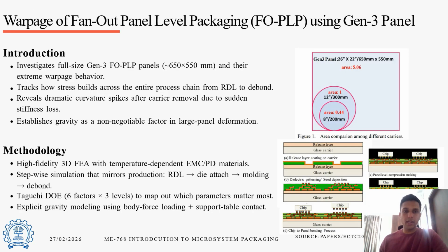In this slide, I'll be talking about one particular paper which discusses warpage of fan-out panel level packaging using a Gen 3 panel. In this paper, the author investigates the full-size Gen 3 panel, which is of the size 650 by 550 mm, and its extreme warpage behavior. You can see the size of the panel in the right side picture. It is considerably bigger than the normal wafers which we use for die manufacturing.